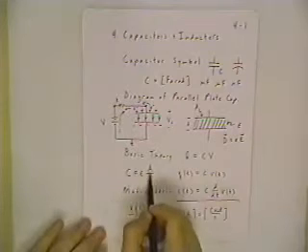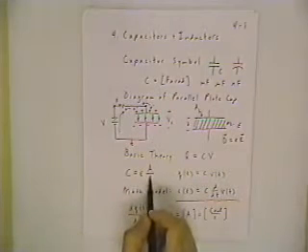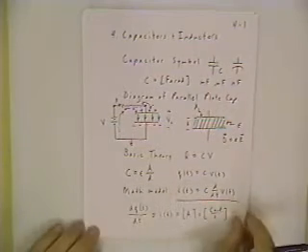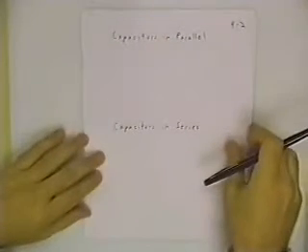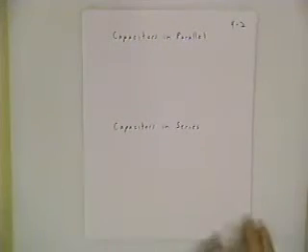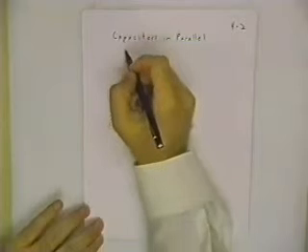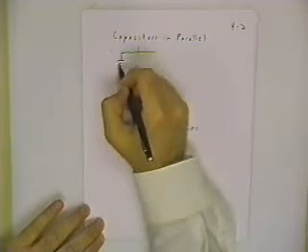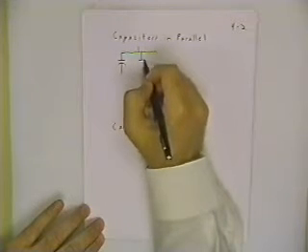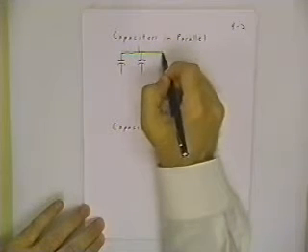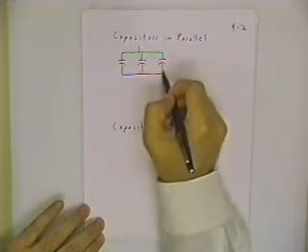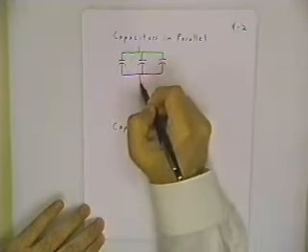Keep this basic model in mind as we talk about capacitors in series and parallel and equivalent capacitances. That'll help you understand where these come from. Okay, first thing is to come up with an equivalent network. If you have capacitors in parallel, then what you're doing is effectively increasing the cross-sectional area for charge to accumulate.